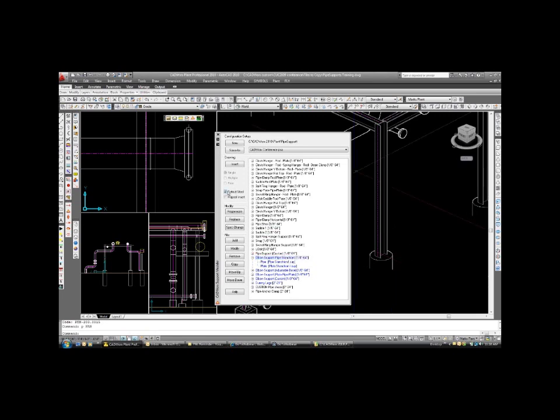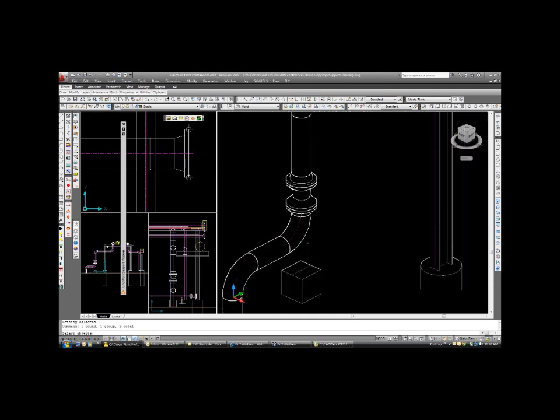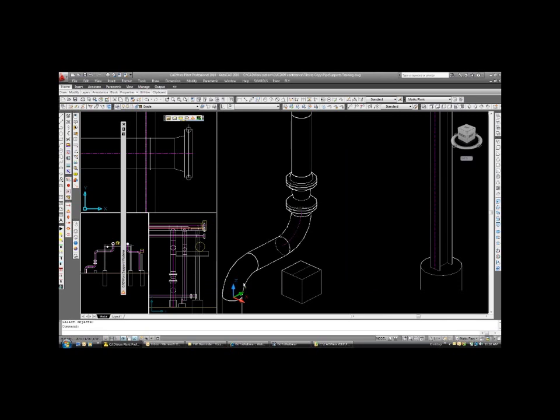We'll say insert. I'm going to take the detect steel off. Well, let's go back to the sample pipe support. We pick the pipe right here in the ISO view. There again, it's going to ask you for different sizes if you have those programmed in. I'm going to select OK. And for right now, I have drawn a midpoint line because I don't have any steel or anything to go to. This is a concrete base. And we let that stanchion get put in right there.